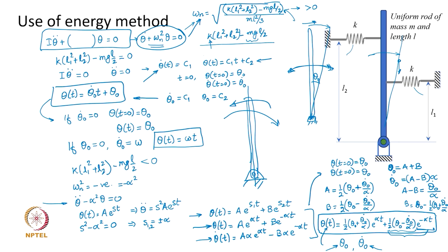So, there is no problem from the second term actually, but the first term here, depending upon the value of initial displacement or initial velocity, even if one of them is there or both of them are there, the response is going to grow. Why? Because the multiplying quantity here is exponentially increasing. The term e to the power alpha t has a positive multiplying component to the t, and therefore, as t progresses, an exponentially increasing amplitude is to be expected.